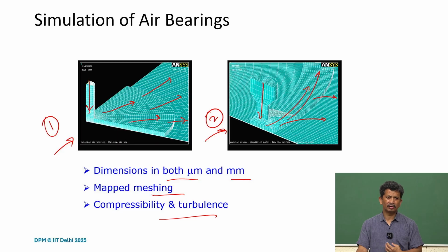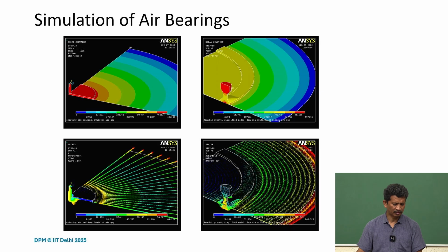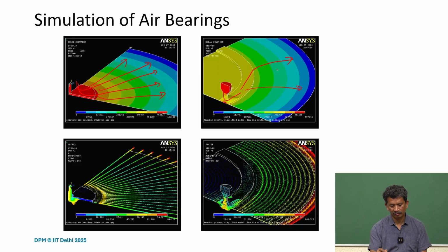But the good thing is, even before we start making these air bearings or air pads, this can be well designed using CAD, and then we can use these CFD packages to do the analysis. So we did that, and from here also is the supply pressure. If you see the pressure distribution, it's quite evident how the pressure is varying from the circular pocket to outside. For annular, I think the inside is more or less uniform, and then it's flowing outside.